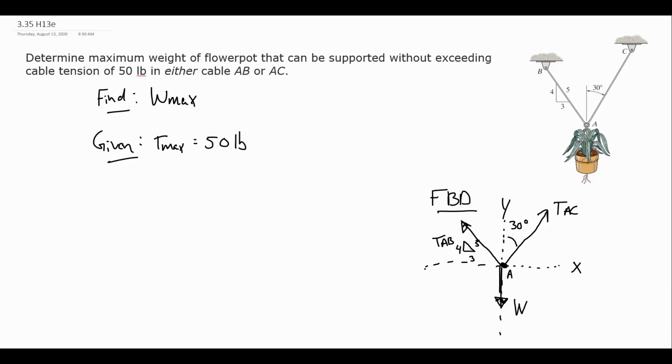So now we have a complete free body diagram for the problem, so we can use that to drive our equation step. So we'll start with the equilibrium equations. Again, these are going to be coming directly from the free body diagram. So equation 1, I'm going to take the sum of forces that act in the x direction. The order we do these in doesn't really matter, but I'll just start with x here. I'm in static equilibrium, so I know that they must add up to 0.